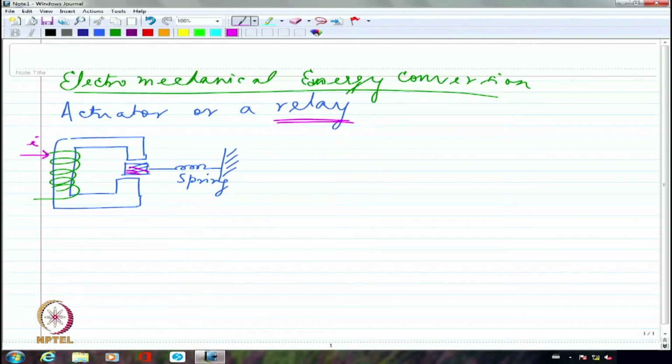For example, if I have a power system which is supposed to be carrying 1000 amperes of current, and the current goes more than 1000 amperes, say it goes to 1200 amperes, then immediately a protection system should act, because it should sense that there is some overload somewhere. Something has been short circuited probably. So the current drawn is heavy. If the current drawn is heavy, I have to make sure that somehow that circuit is cleared. So unless the fault is cleared, I can't activate that particular load again.